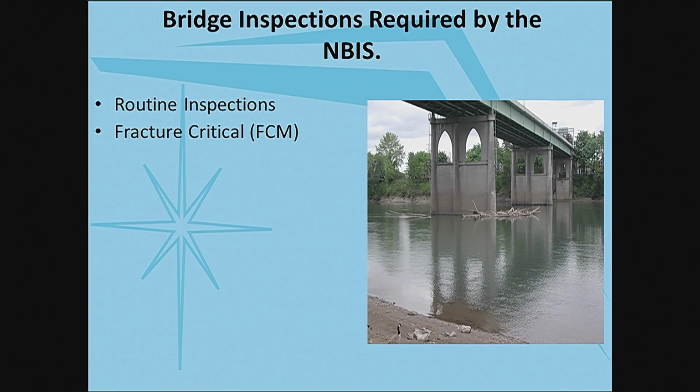And it has to be within hand's reach. You have to be within 24 inches of the member. So no drones, no anything like that. I mean, you can find indications with drones, but you have to be right there, feeling the member and touching the member.